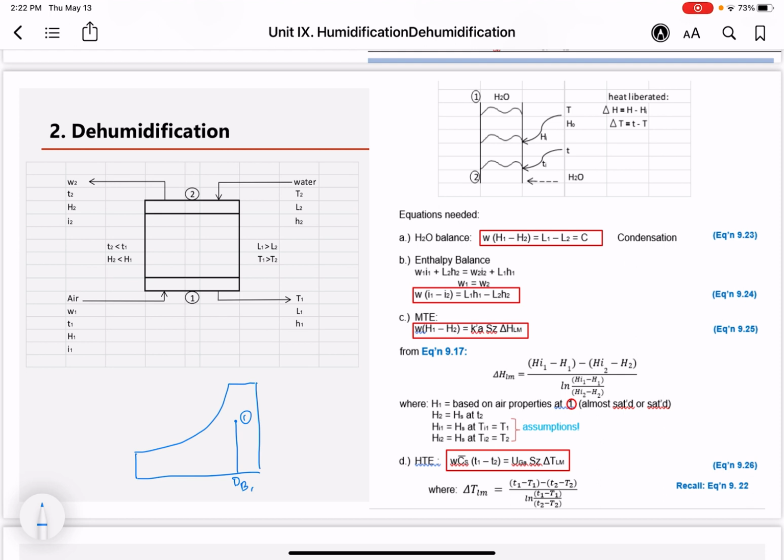All you need to do is make a, so cooling and dehumidification to. You have here the enthalpy ulit, kung naka-project doon, this is your enthalpy 1. All you need to do for cooling is project here up to a saturation temperature at this point. So this becomes my dry bulb 2, and this is your wet bulb 2 and your dew point 2.